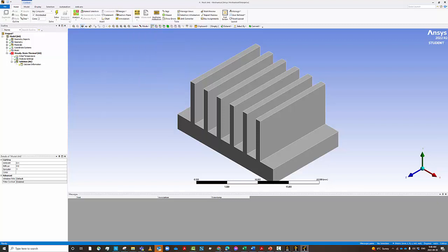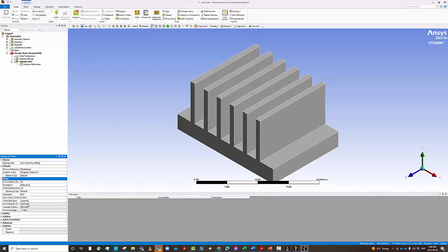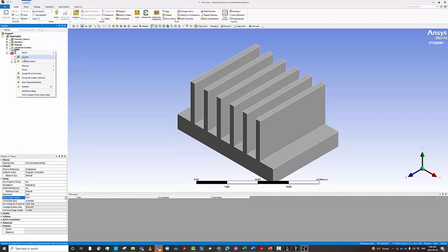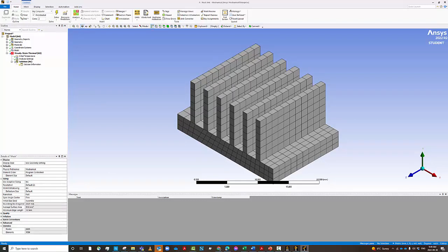Now we go to generate the mesh, and in the mesh here we can go, and of course this is statistics. I told you about different techniques for meshing before, but you can test others as you move on. You see here, this is a coarse mesh. We can change that to a fine or medium mesh. This is one way. And if you go to that, you're going to find that the minimum edge length is 1. So let's mesh with that and see what we get.